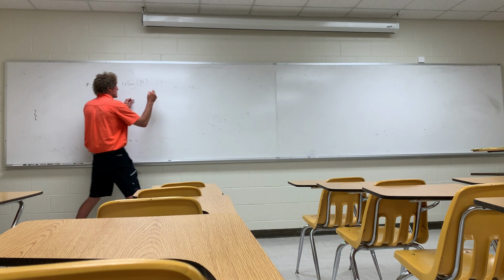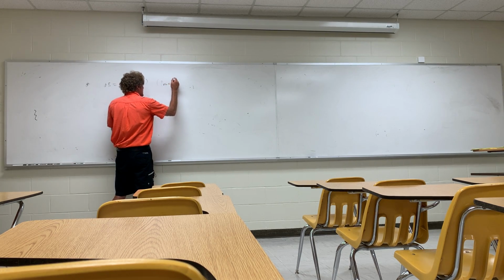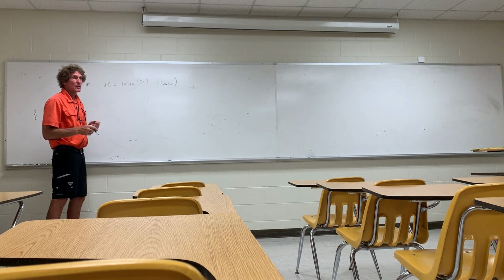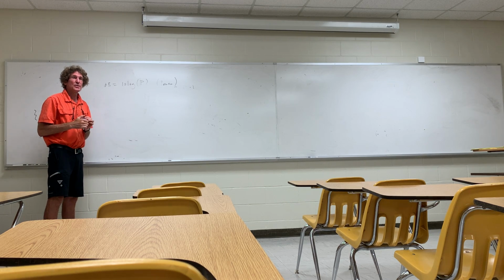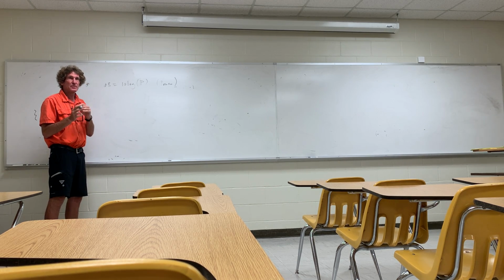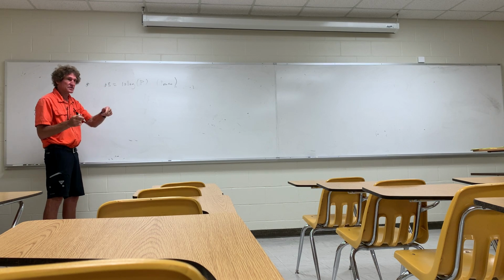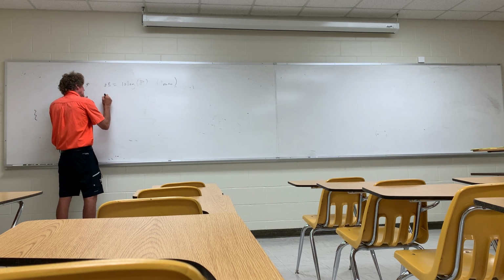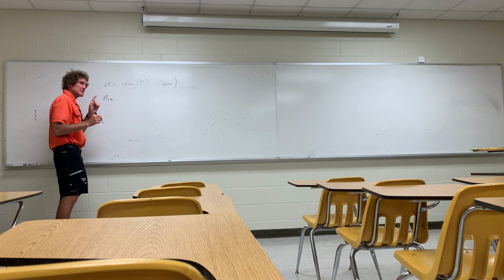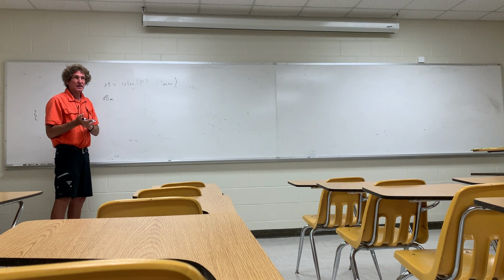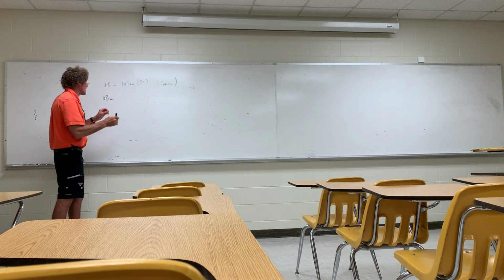This is for power. When you talk about power, most of the time they do it by talking about something that's called the normalization relative to something. So the term dBm is often used. That's dB, where the power itself is divided by 1 milliwatt.